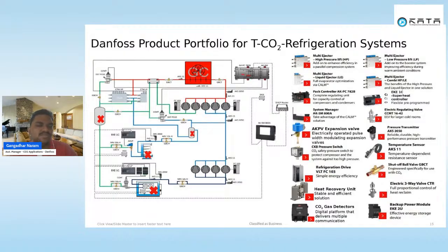But the remaining nearly 85 to 90% of components are ready for CO2, and we are ready for the future to give all the applications, all the components which are utilized for CO2 applications. For example, we do have the compressors, we do have the VFDs, we do have the heat exchangers, which are rated for 130, 140 bar applications.